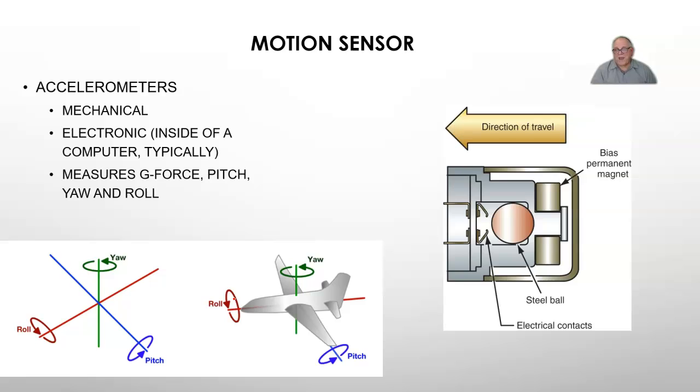If you started to panic because somebody suddenly pulled in front of you and you slam on the brakes, the computer's going to look at this. It's going to put more pressure to the outside wheels because the car's leaning over that way, less pressure on the inside. The computer's going to adjust this. If you have a full active suspension system, the computer can actually pump up the shocks on the outside, drop down the pressure on the inside, and literally make the car lean into the turn.